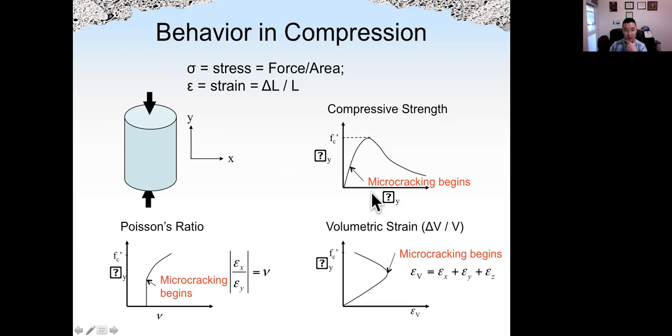Initially the slope of the curve is pretty much straight, which means the concrete is a near-elastic material. After microcracks occur, the slope becomes smaller. And after reaching the ultimate strength, the concrete can still somehow resist the load until the final failure here.